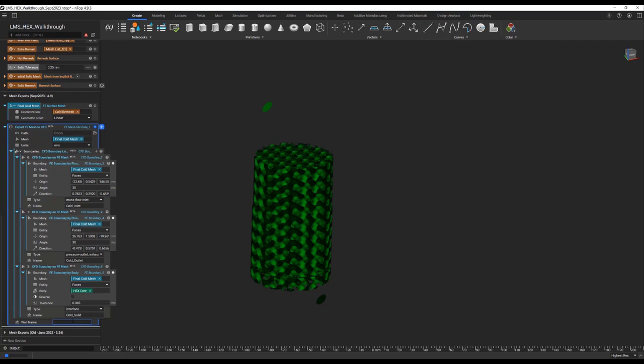It'll get labeled as default if you don't define a wall name. However, if we get into importing multiple bodies into Fluent, it's extremely beneficial to at least have the word cold in here. So generally I'll just come in and say cold default. So that way you'll see in Fluent when we get there, we're going to have 4 different boundaries: the cold inlet, the cold outlet, the cold to solid, and cold default named selections.